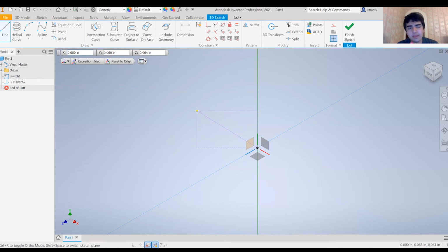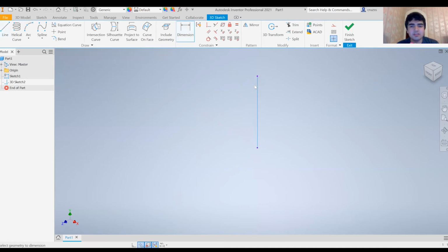And 90-degree angles overall are usually what you're going to be using when you have 3D sketches, for reasons I'll talk about in a second. So this is probably a very commonly used example of how you would use a 3D sketch. What I'm going to do is create a bunch of lines. Of course, I'm going to make them all 1 inch long to simplify it.